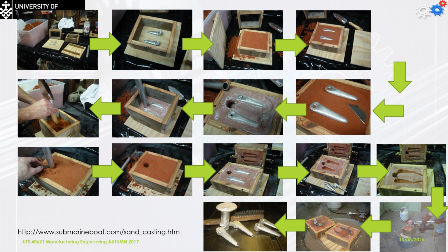Close the cope and drag. Pour the metal and leave it to solidify. Open the box and take the casting out. That will be the initial shape with the pour and the riser, and then we can cut them out to have the handles. Very simple steps.